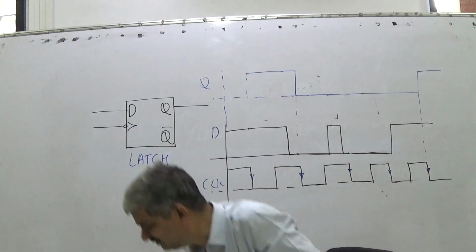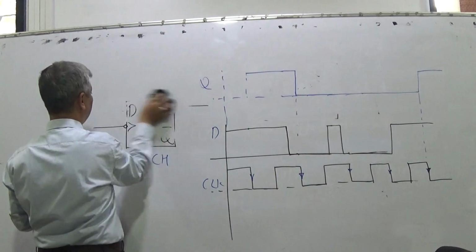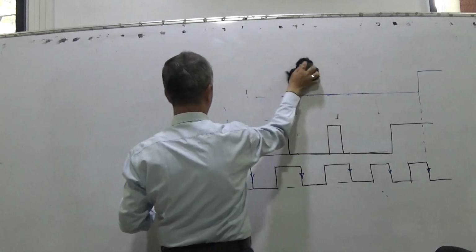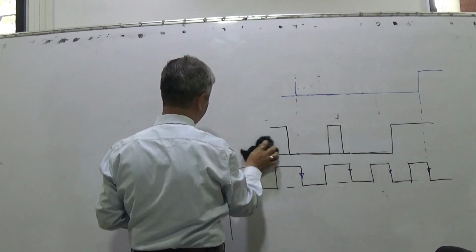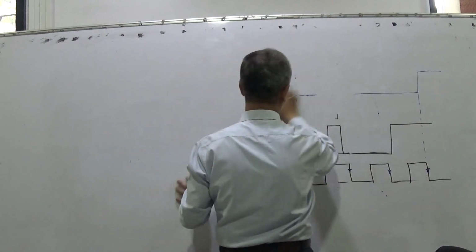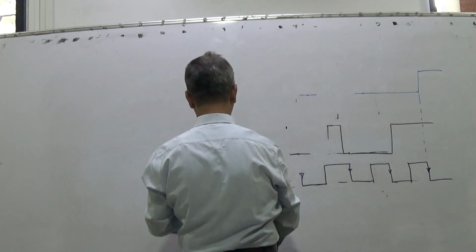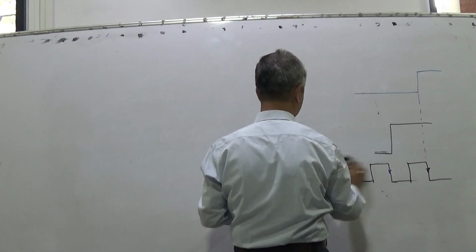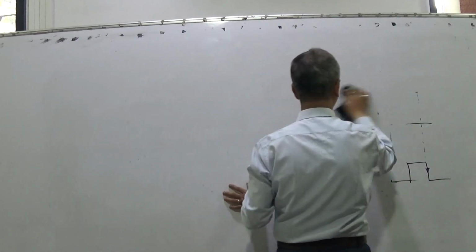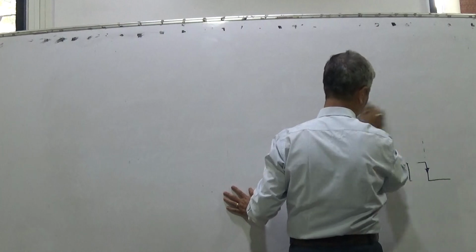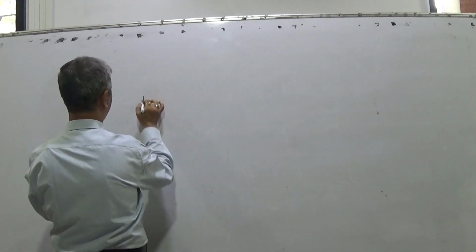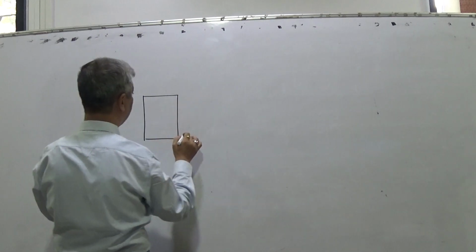So this is the concept. And shift register. What is a register? Simply, we are having, let us say, it can be 4 bit, 8 bit, 16 bit, it can be 2 bit also, but 2 is too low. So normally we consider a 4 bit register. A 4 bit register means 4 D flip-flops.